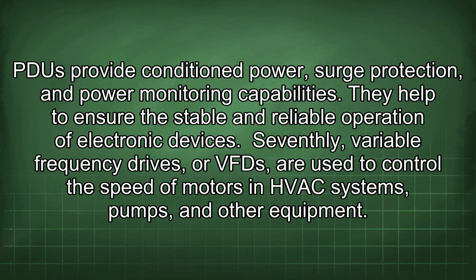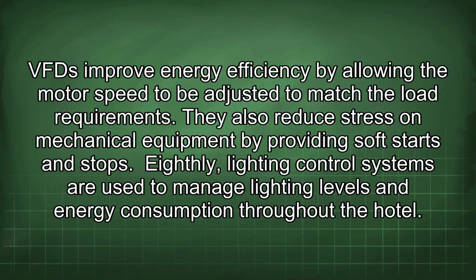Seventhly, variable frequency drives, or VFDs, are used to control the speed of motors in HVAC systems, pumps, and other equipment. VFDs improve energy efficiency by allowing the motor speed to be adjusted to match the load requirements. They also reduce stress on mechanical equipment by providing soft starts and stops.